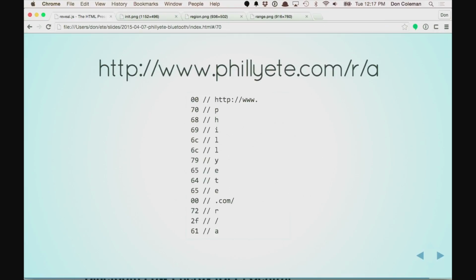So they use a compression scheme on the URLs. This is very similar to what in NFC, if you have a URI, they compress that so you can fit it on an NFC tag, and they basically do substitution. Do the same thing here. So http://www. gets all replaced with the 00. You put that in there, we've saved a whole bunch of bytes there. We put in the bytes for each of our letters, and then once again, when we get to .com/, there's another substitution of also a 00 in that case.